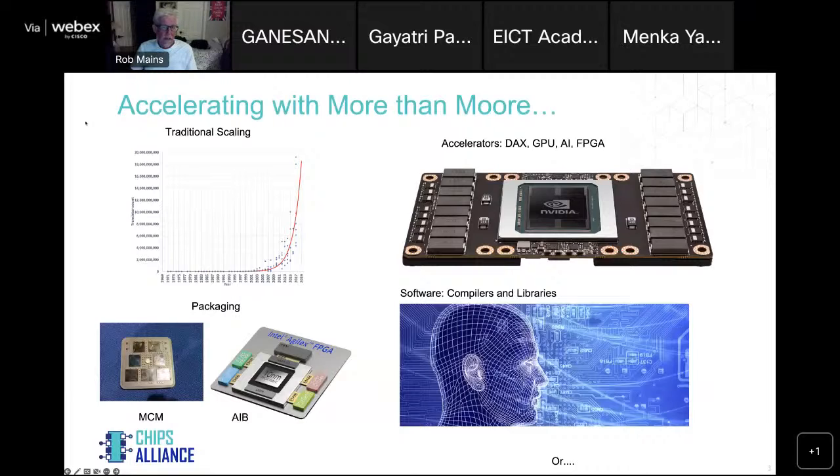Another advent that's occurred to help alleviate the challenge with process scaling and to improve performance is the notion of accelerators, right? So custom accelerators have been created. It could be something like Oracle created, which I was part of on the M7 chip, which was the database acceleration unit, where instruction traces from actual database calls were captured, and then it was determined in hardware how to help accelerate that. So a special acceleration unit was built and put in the M7 microprocessor, or Spark microprocessor.